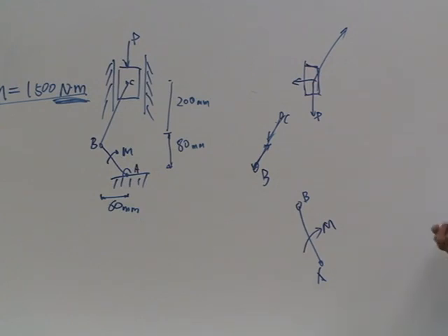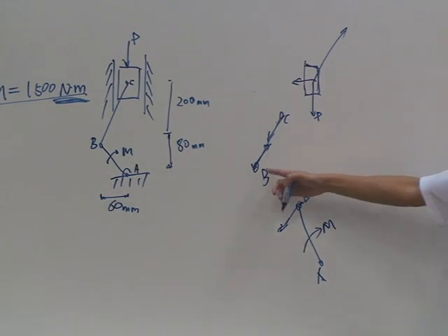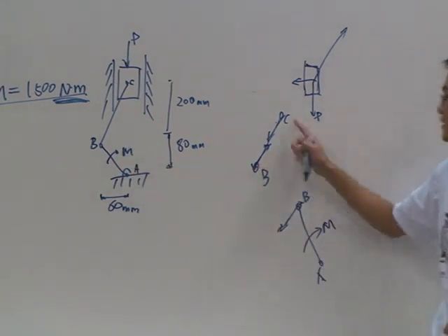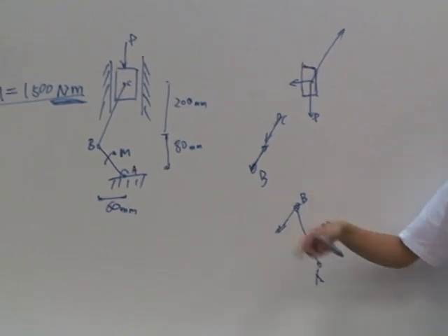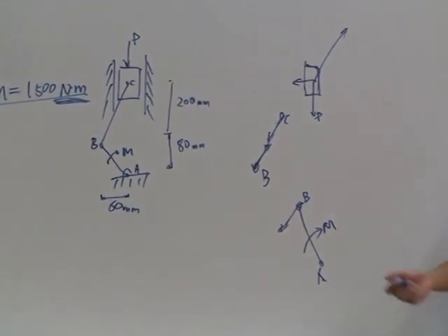What are the other forces? What are the points of contact? You might give me any forces. Point B, okay. What direction? Along the BC. Along the axis of BC, correct, because it's a reaction of the force here. This member gives BC a force here. So definitely this member will give it a counter force here, which, according to Newton's third law, will be in the opposite direction with the same magnitude here.